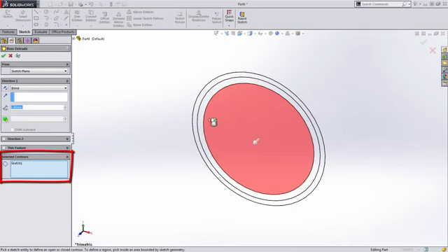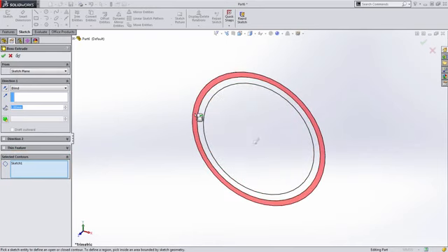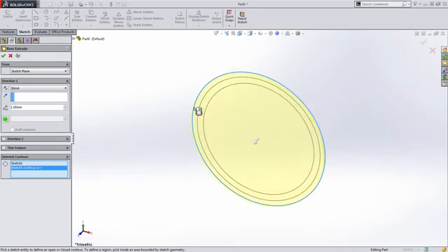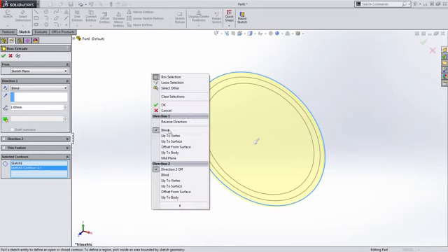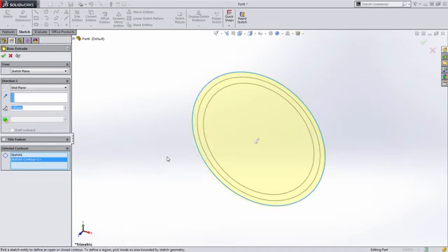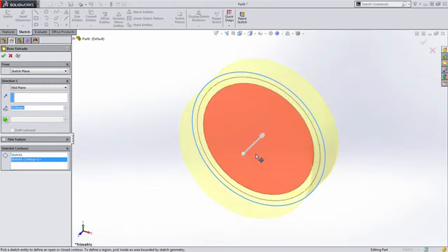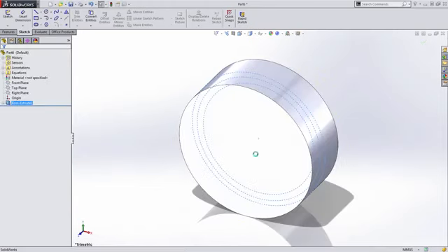Selected contours allow you to select just portions of your sketch. Now, we could select each one of these regions, but you can also select the outside diameter to capture that whole circle. I'm then going to right mouse click and choose a mid-plane extrusion type, and I'm simply going to drag out this value to 20 millimeters and right click to finish it.